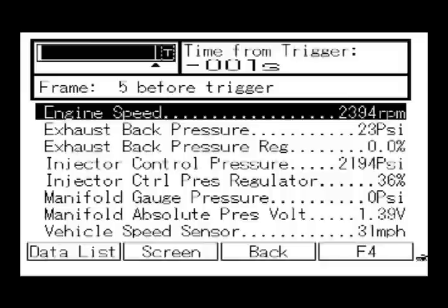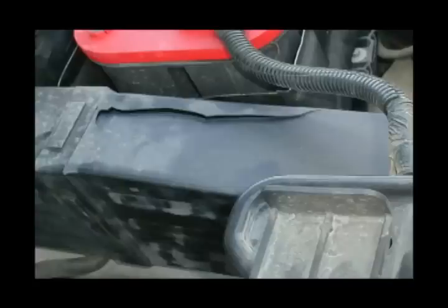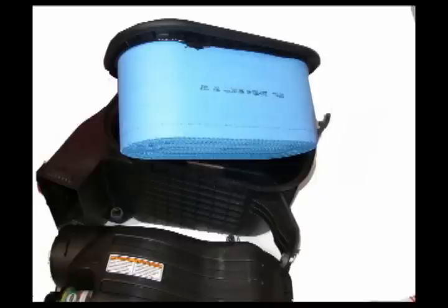Now that we know where to look, we notice that the air filter itself is clean, but we also see that there's physical damage on the snorkel, which in this case wouldn't cause the problem. When speaking with the customer, we learned that a new Donaldson filter had been installed several months ago, before the symptom began.